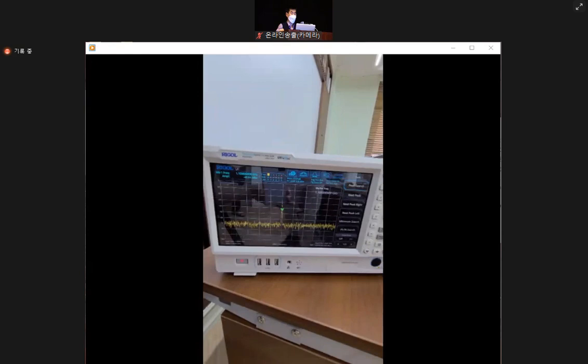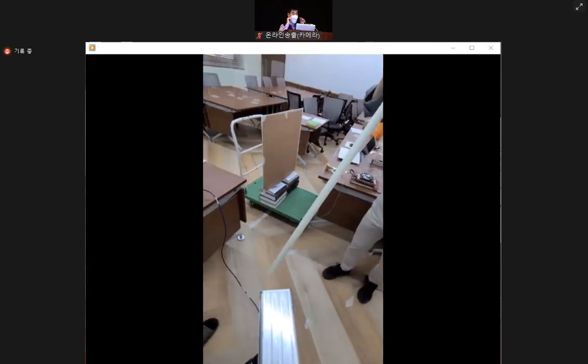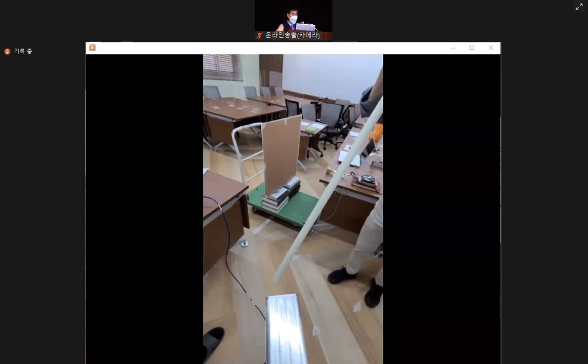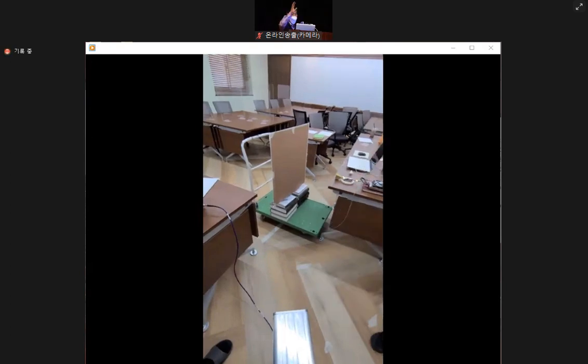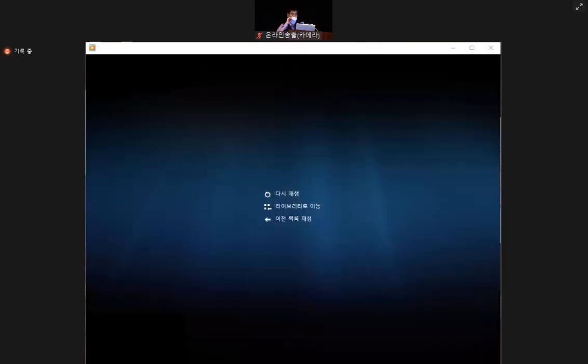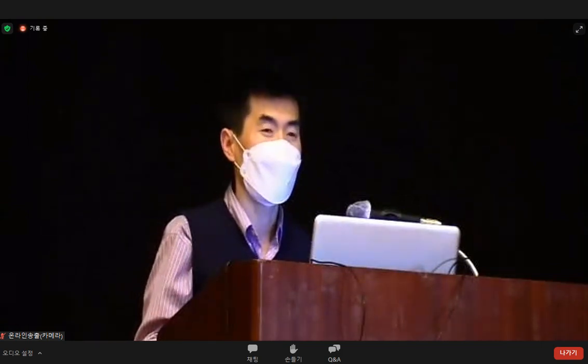By watching the probe move from the desired angle to the upper angle, on the spot, it is hard to read the tiny numbers of signal strength. But I am definitely telling you, the received power has gone down, as we expected. At 45 degrees of observation, that was the best and highest in strength, around minus 40 something dBm. But at other angles, such as 20 degrees or 60 degrees, it will go down by 10 dB like that, or more than 10 dB.